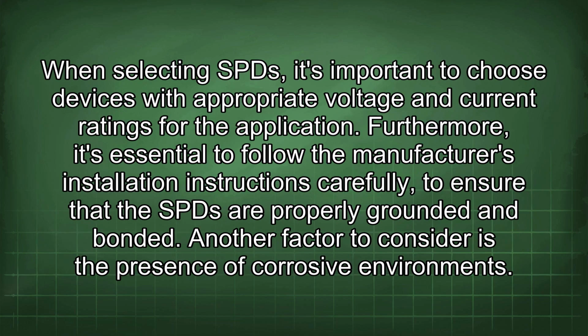When selecting SPDs, it's important to choose devices with appropriate voltage and current ratings for the application. Furthermore, it's essential to follow the manufacturer's installation instructions carefully to ensure that the SPDs are properly grounded and bonded.